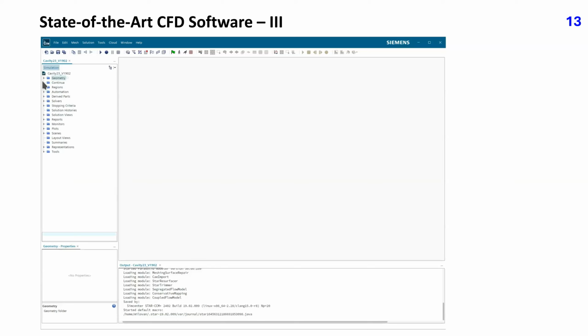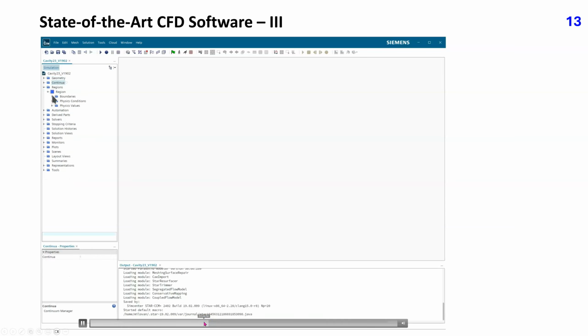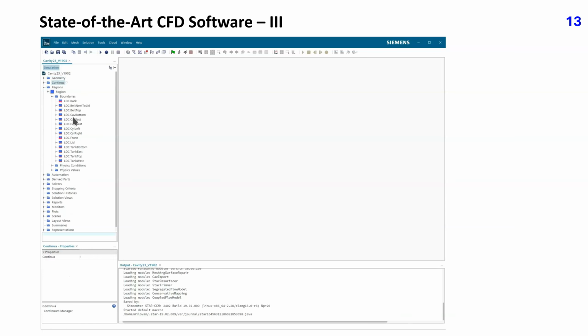The next step is to define physics models governing the fluid flow. Present flow is steady and laminar, a coupled solution model is used, and fluid properties are selected to obtain the desired Reynolds number. The CAD path describing the flow domain has been earlier assigned to flow region.